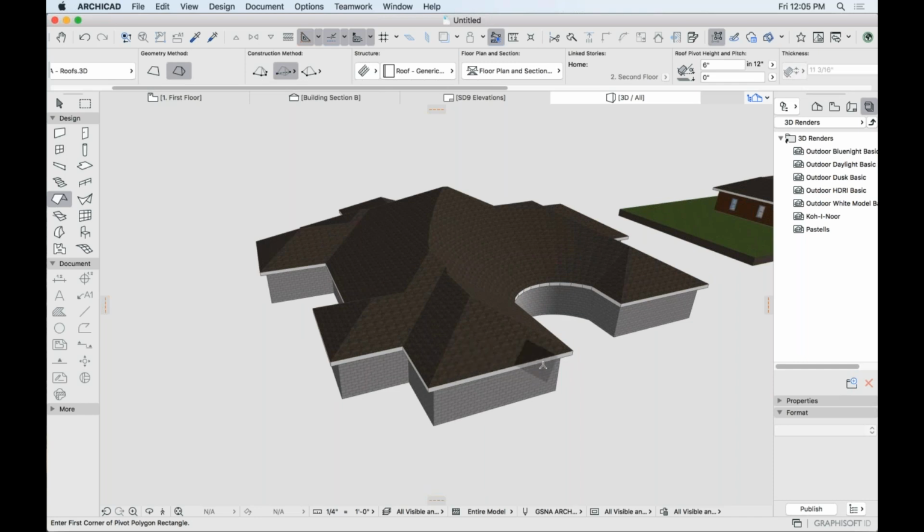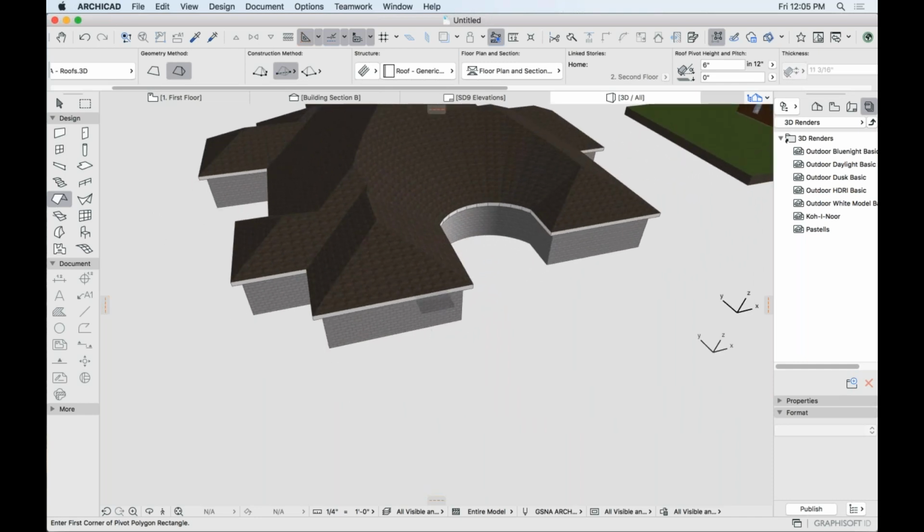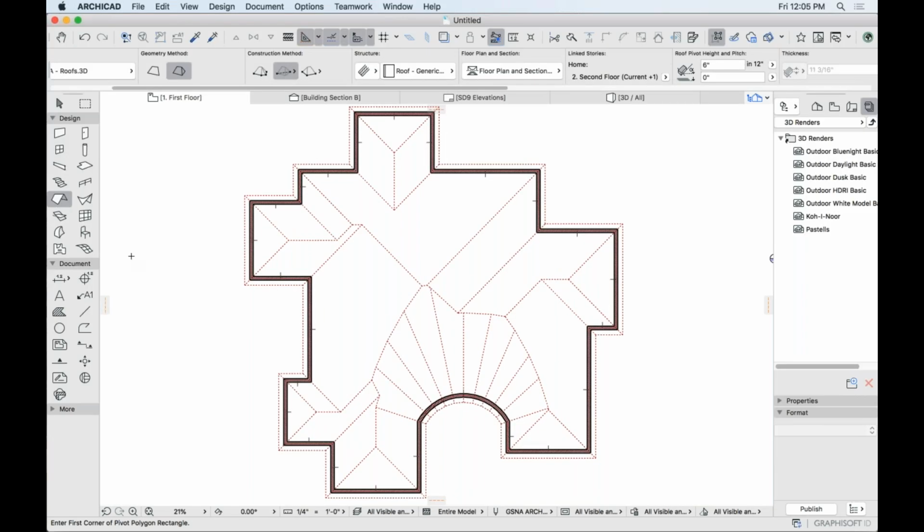And then you can use ARCHICAD to edit that and change that and bring this down to construction document level. So that's the space click. It basically works for any, let's talk about which tools it will work for. It'll work for the wall tool, the slab tool, railing, roof, the shell, curtain walls, morph, and mesh. Okay, so it doesn't work for an object because a door is a door.